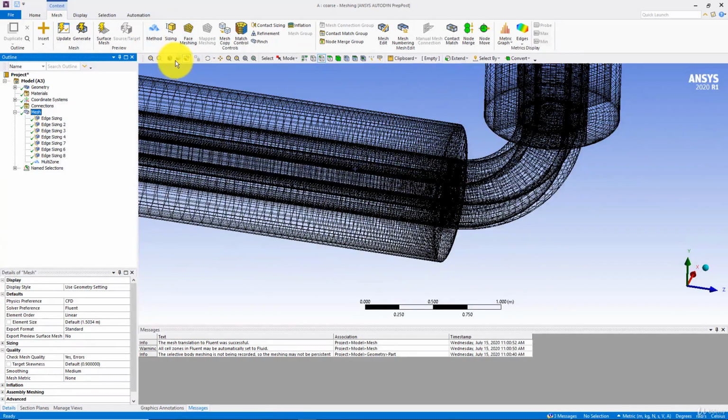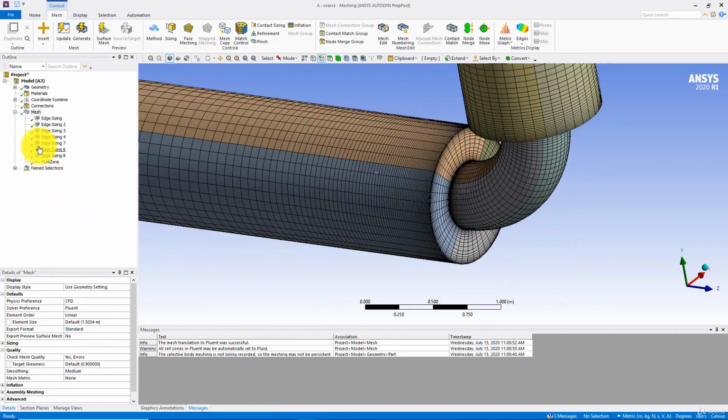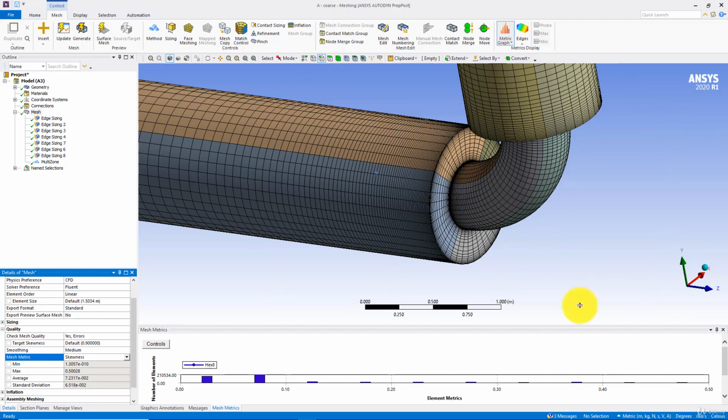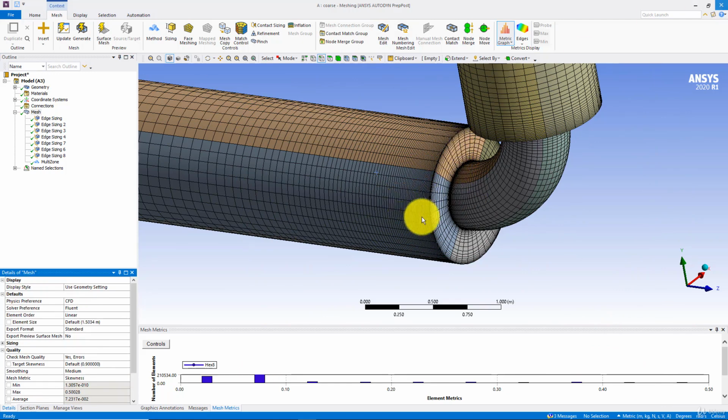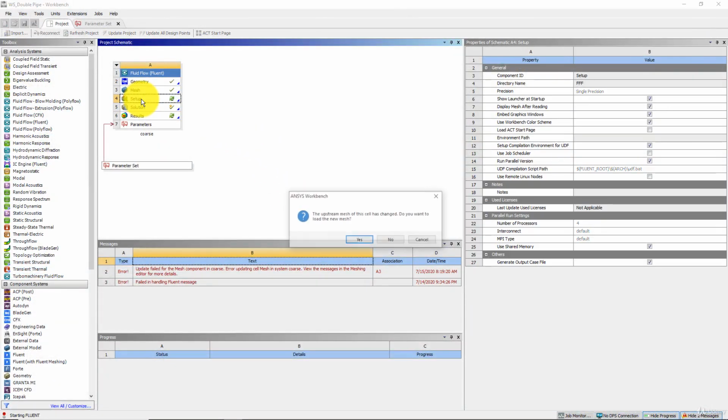And also change from wireframe to solid view. And now again check the mesh quality by clicking on the mesh. And from quality, click on skewness. So I wanted to see the mesh metric as skewness. And you can see now the maximum skewness is 0.5, which is somewhere maybe on these parts where we have some angles. And now I turn off the Ansys meshing software, and I will open the setup file for Fluent.